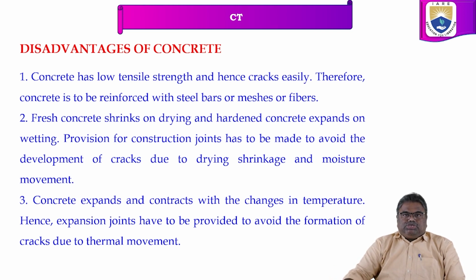The fresh concrete shrinks on drying. Hardened concrete will expand on wetting. So provision for concrete joints has to be made to avoid the development of cracks due to drying shrinkage and moisture movement.